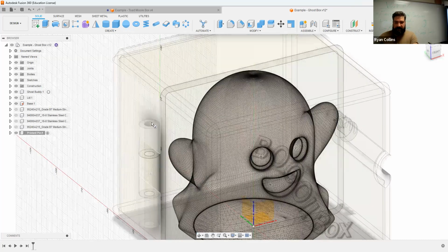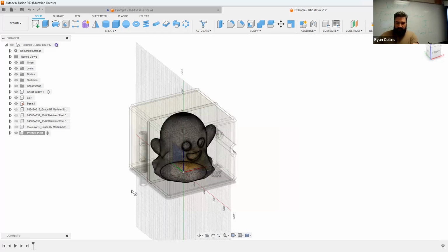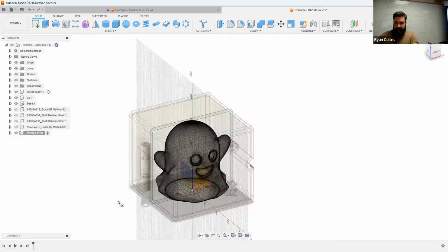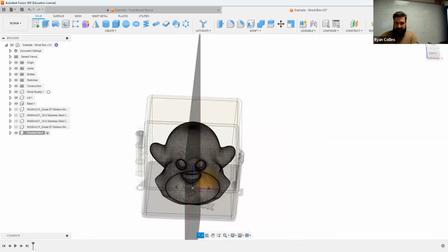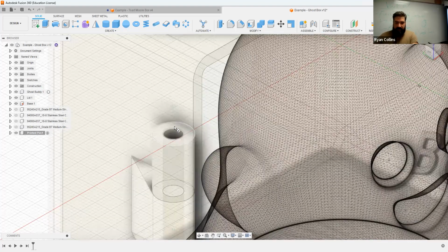Now you can either start it in place or just somewhere. If you want to use joints to snap it in place, great. Let's do exactly that. Now, see, I'm going to have trouble selecting something, so let's just snap it in place. So I'm going to select right on top of this hinge part as my plane. That's what it will create.